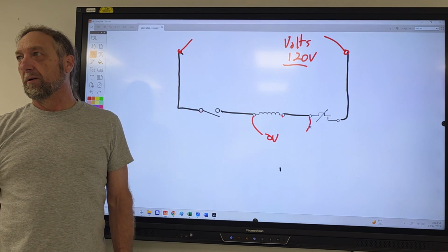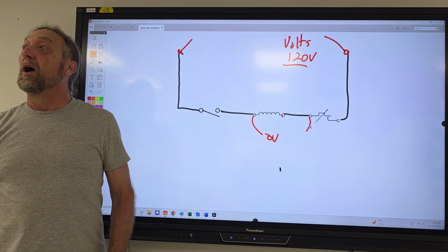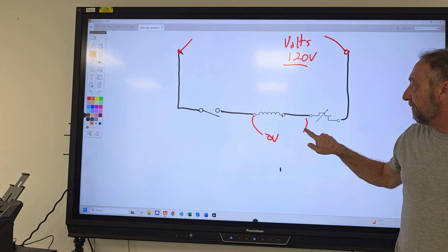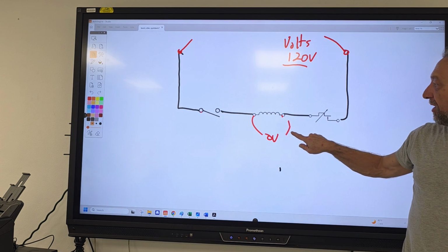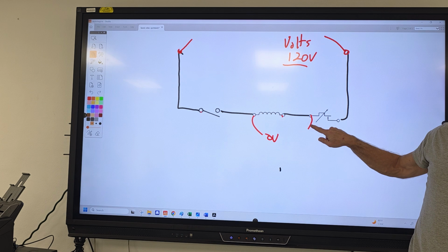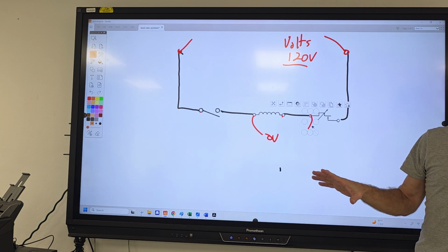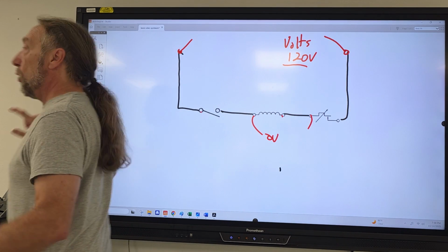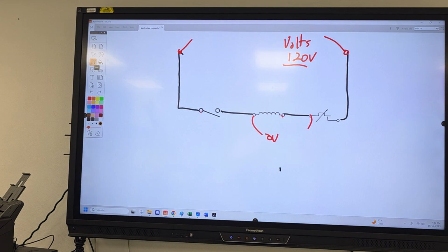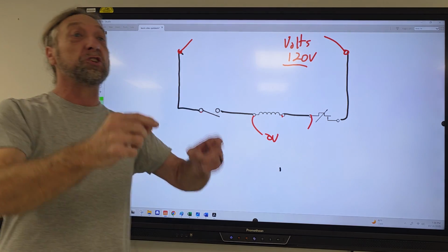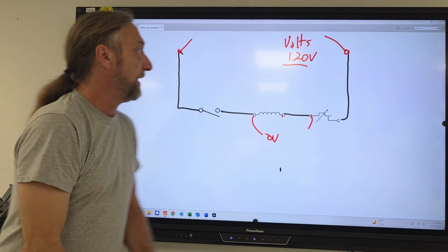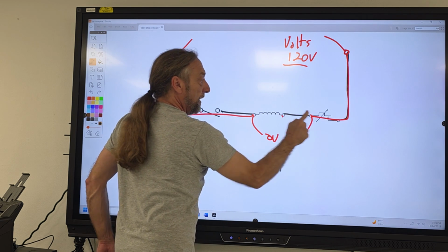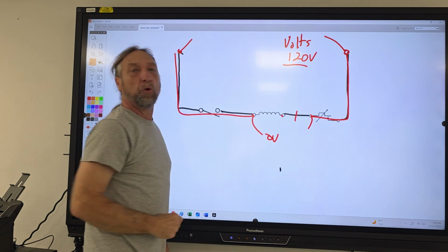What am I checking? You're breaking down your wire line. Okay, so this is what it is. If I have 0 volts here, but all of a sudden I get 120 here, what does that mean? That means your wire is bad. That wire's bad. Yeah, but that's not how we look at it. Because voltage is telling me what's good. And I know that it's voltage from here to here, but I don't have it here, so now I know the wire's broke.